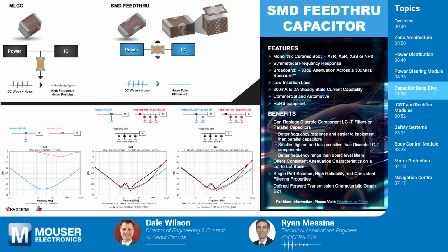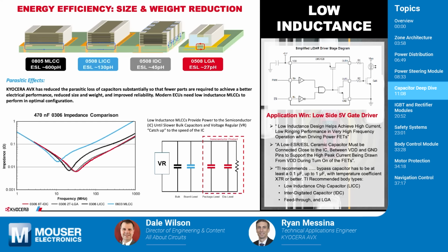Right. So the equivalent circuit is a series inductance and a parallel capacitor. So you'd have an inductor in series and then a parallel capacitor. That would be how you would model that on LTspice or something like that. Interesting. And you get all that in one tiny package. One tiny package. That's why I love this part. It's really neat. I had never heard of feed-through capacitors before. At least I've heard of them, but never dived in to see what they do. And so this is really fascinating to me.